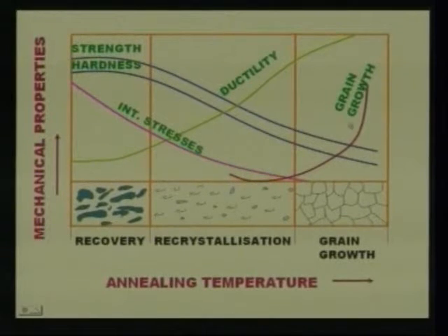And now you see the grain growth will not take place in the recovery, but as the grain growth starts, first it increases and slowly decreases, and again it starts increasing, therefore the crystal size increases. Therefore after recrystallization if you increase the temperature, it is disadvantageous in many applications. So this is the mechanical properties versus annealing temperature.